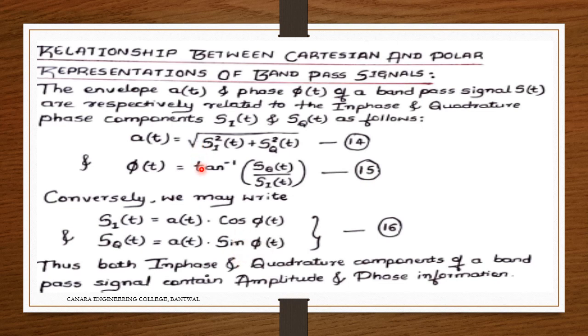So instead of representing the whole thing in a long equation, we can represent it in these terms. We can represent it in the complex form, and that complex form can be converted to get only the natural envelope. We can also represent it only in terms of the natural envelope and the phase.